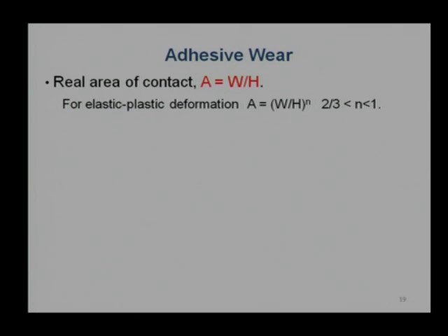But we know very well there will always be some asperities, of very high height or low height. Not all asperities will undergo plastic deformation. There will be contact at the elastic limits also, and separating two surfaces at the elastic limit will not be much problem. Effectively, the area of contact will reduce. If there is a plastic deformation, naturally more area will be in contact. There is a deformation, some flattening of the surface, so more area of contact will be there.